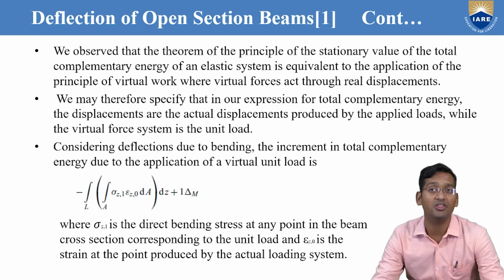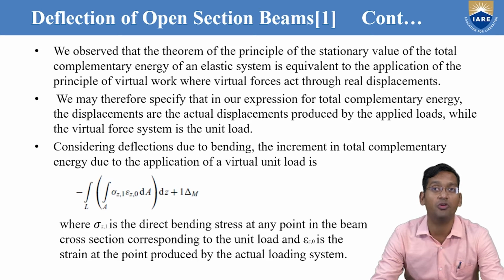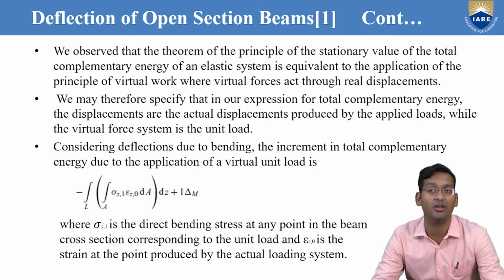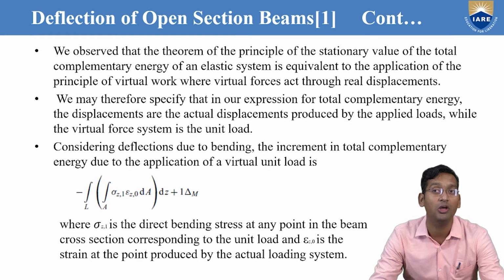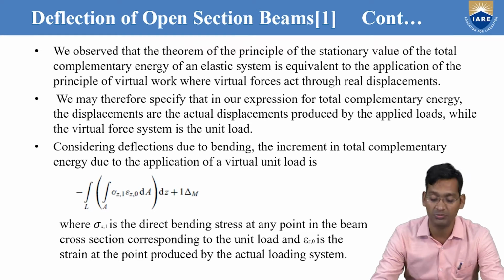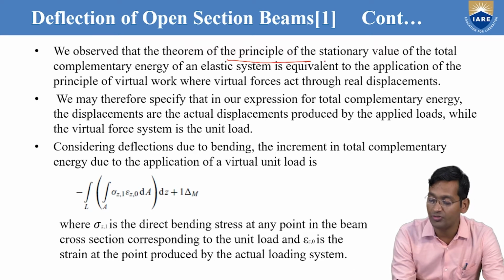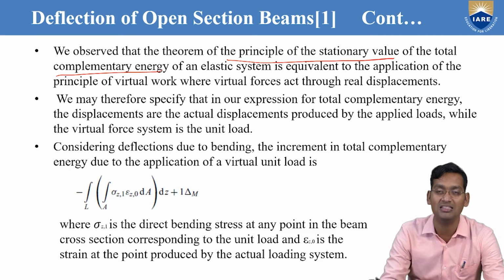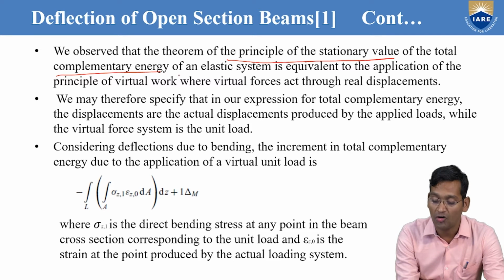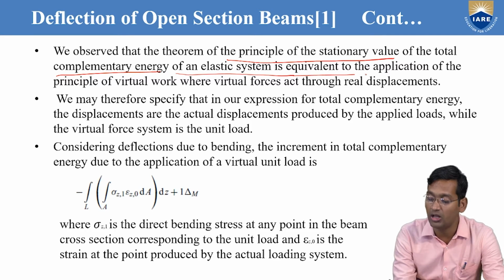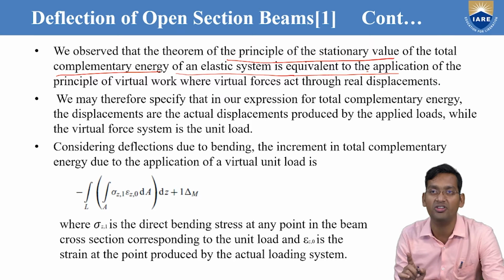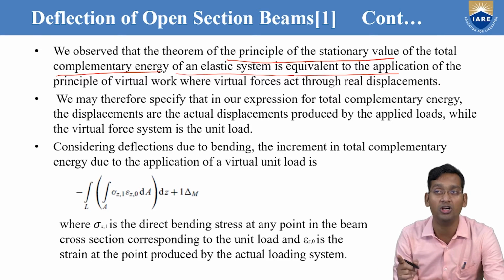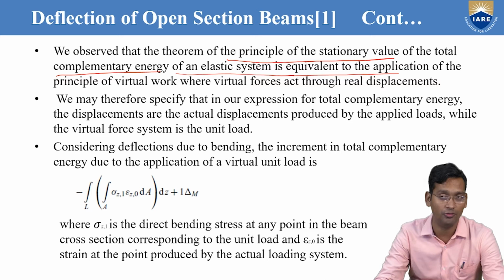We observed that the principle of the stationary value of the total complementary energy of an elastic system is equivalent to the application of the principle of virtual work, where a virtual force acts through a real displacement. So total complementary energy is equivalent to the principle of virtual work.